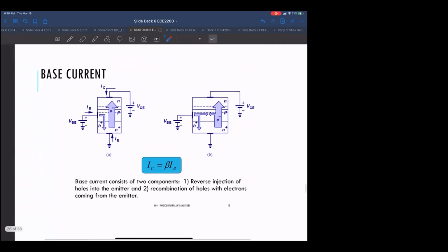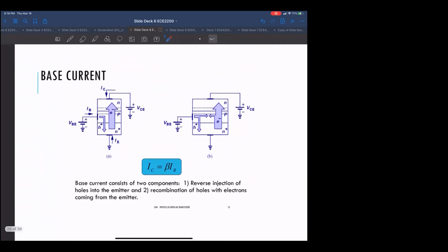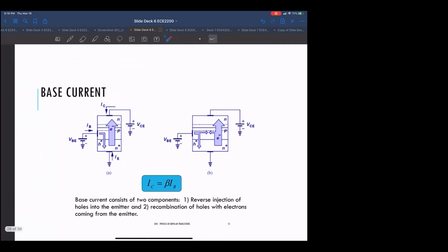No, hey, it's here. So the base current. Okay, so now the base, we said there's a very small base current that flows into the base and from the base to the emitter. Remember this base current was going here, and there was a corresponding electron current that was much higher going from the emitter to the base. Okay, so if you look at the base current, it's much, much smaller than the collector current.